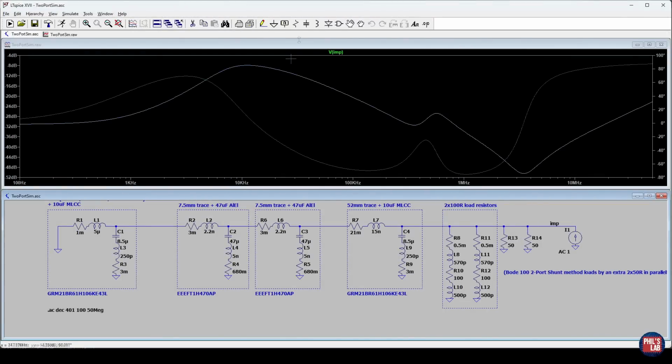We have the low frequency performance dominated by the inductance and bulk capacitance up to the crossover frequency at around 10 kHz. Then the decreasing impedance profile, we have a parallel resonance, a series resonance, then we have a multi-layer ceramic capacitor self-resonant frequency, after which we go into the equivalent series inductance part of this impedance magnitude.